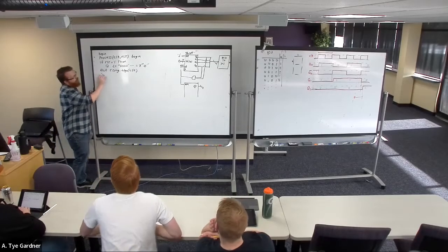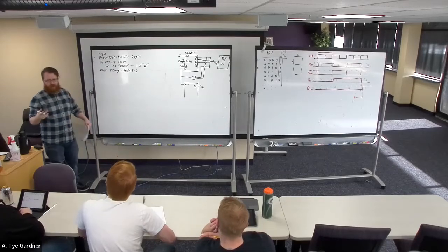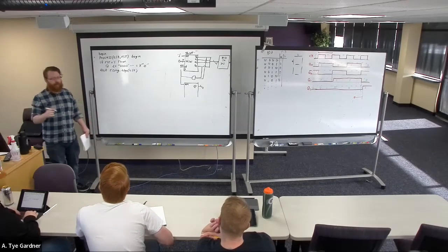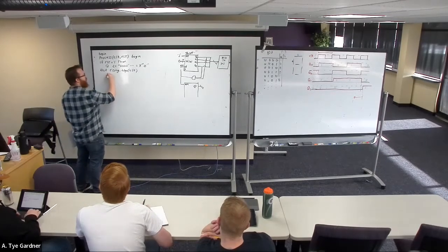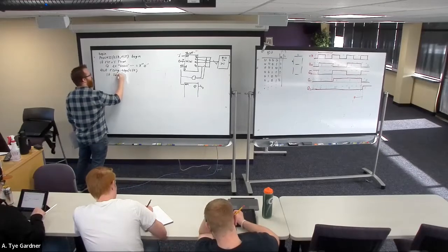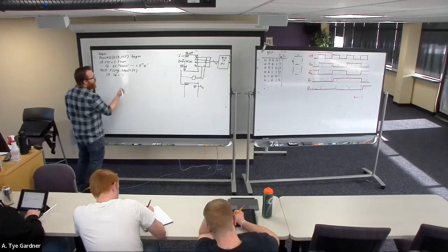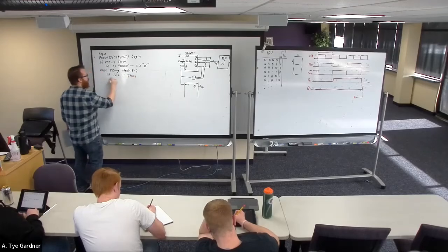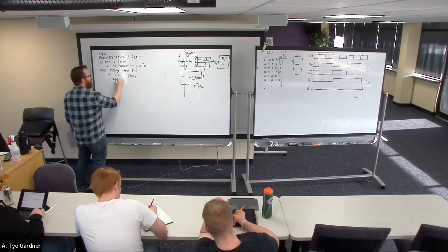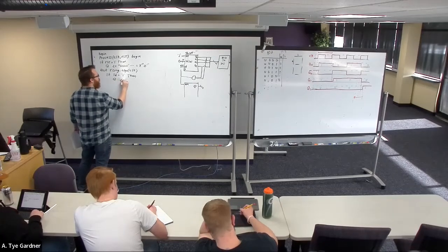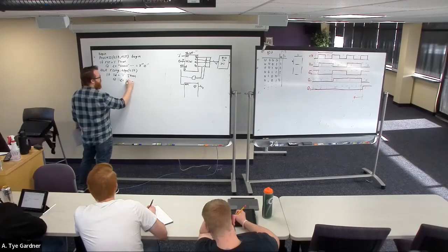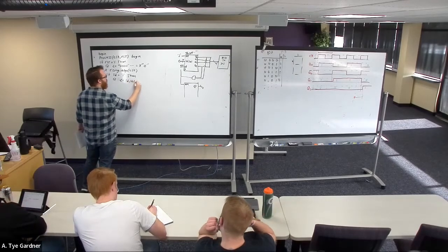Okay, so now we get that rising edge of the clock. What do we do? Well, the first thing I want to do is check if there's a load, because I've designed a synchronous load. So I say if load equals 1, if load is true, right? If I send it back around, then Q gets assigned, oops, I'm going to leave a little bit of space after the Q, gets assigned to, well, whatever load val happens to be.